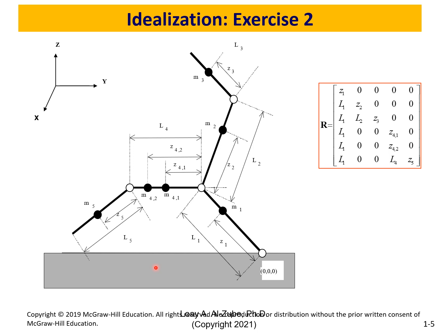Now, if you want to have the generalized mass matrix, we need to have a diagonal mass matrix. So how many masses do I have? 6, right? M1, 0, 0, 0, 0, 0. And then, the diagonal matrix, I'll put the masses on the diagonal and everything else is 0. And then you'll have M2, right? 0, 0, 0, 0. And at the end, you'll have 0, 0, 0, 0, 0. That's, let's say 5, because you have two 4s, M5, right? So that's a 6 by 6 matrix, diagonal matrix.